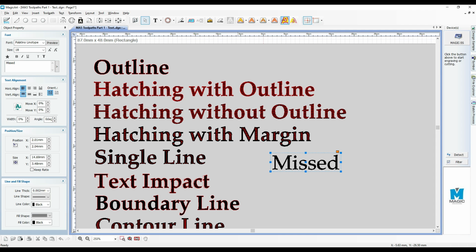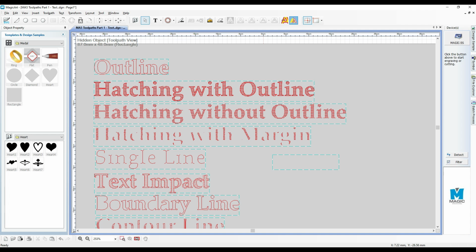Now, somebody else might have more information on this, but I find that's not really useful unless you're actually doing a cut, so using the rotary spindle, because it relates to the width of the tool that you're using, the cutter, and it will estimate whereabouts the boundaries of that cut will be. From what I understand, if anybody would like to comment anything different on that, I'd be interested to hear that. And then this is your show toolpath only, which we've used. Just escape from that. Sorry.